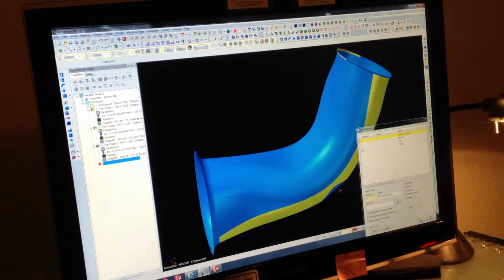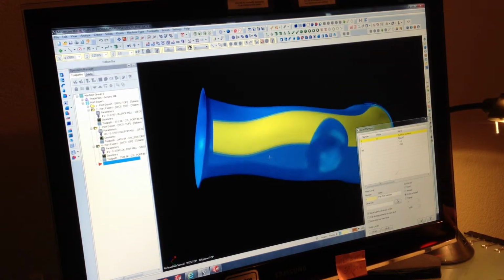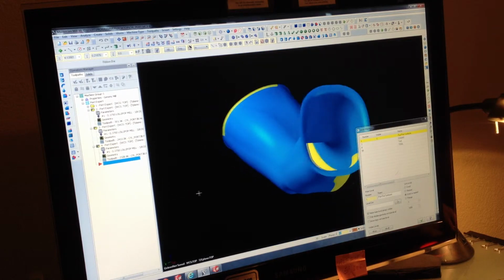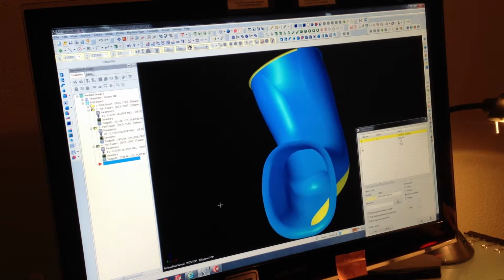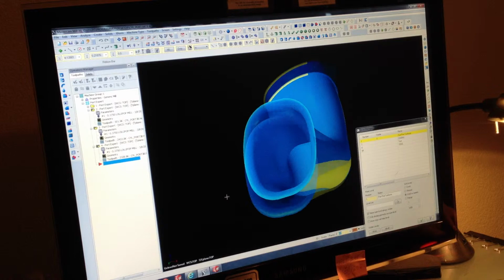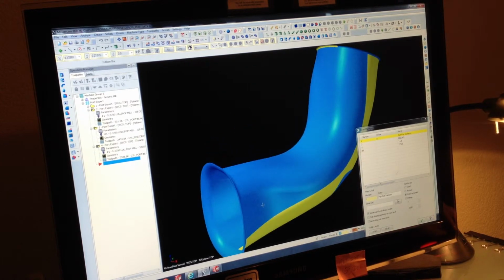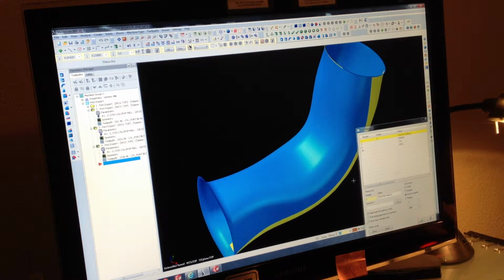Last session, we had to create some additional geometry to the cylinder port in order to create the vectors and create a spline in the middle. You can use a Mastercam automatic spline. It mostly works, but the only problem here is this part has a little tweak inside of it. It makes it a lot more complicated because the tool has to clear the bump in the middle, and you shouldn't hit the top. So it makes it a little more complicated than automatic spline creation.